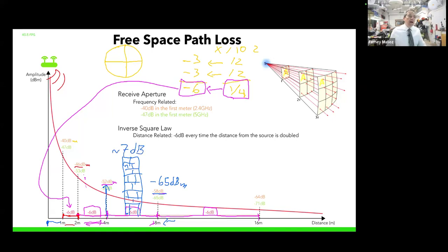Like when you go to Ekahau and it says, oh, this is a 3 dB drywall, or this is a 10 dB brick. That's what they're saying. A signal through this obstacle loses 10 dB, or loses 3 dB, or loses whatever number it is. Same in Hamina. In Hamina, you can go in and create things, and then it says, this wall loses 2 dB, or it's a really thin pane of glass, it loses 1 dB. Okay, that's how much energy is lost across those.